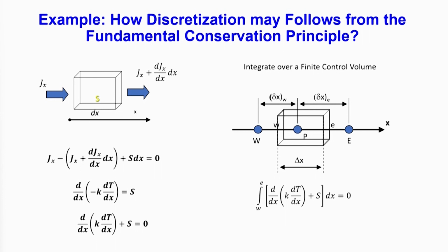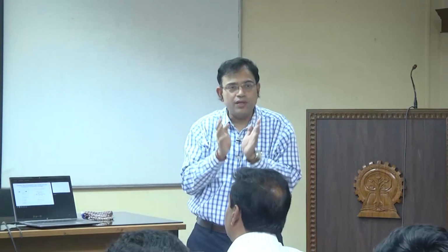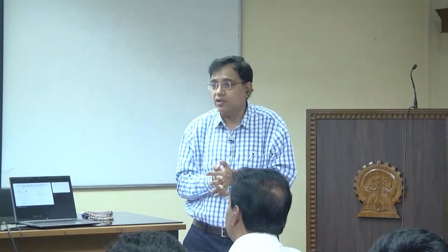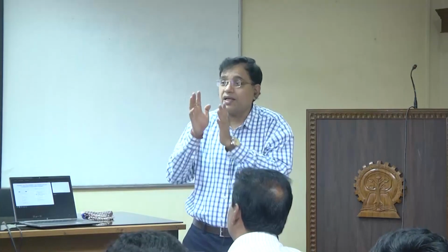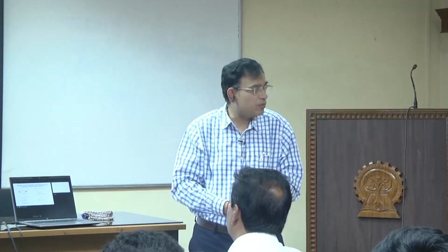This is the principle of conservation of energy. By integrating it over this control volume, you are ensuring that this conservation law is fulfilled, and your domain is a collection of many such control volumes. If it is fulfilled for one control volume and you sum it up for all control volumes, that means you have a mathematical foundation, in fact a discretization foundation, which is physically adhering to the principle of conservation, and that is why this method is so physically appealing.